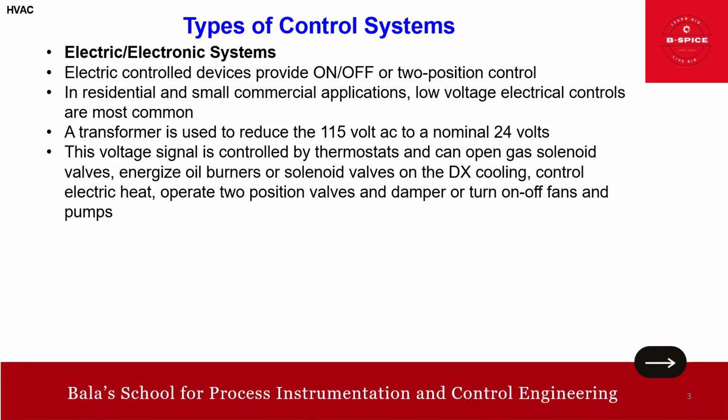Okay, so how it works basically, I think it's beyond the topic, but still I will cover this. See, there are four phases, right? One is evaporation, compression, condensation, and expansion. So in evaporation, the refrigerant absorbs heat from the indoor air as it evaporates in the cooling coil, cooling the air in the process. Then the refrigerant, now in gas form, is compressed by the compressor, increasing its pressure and temperature.